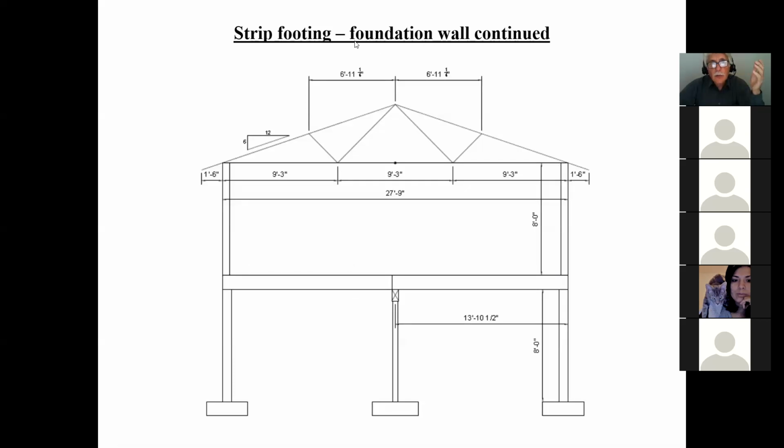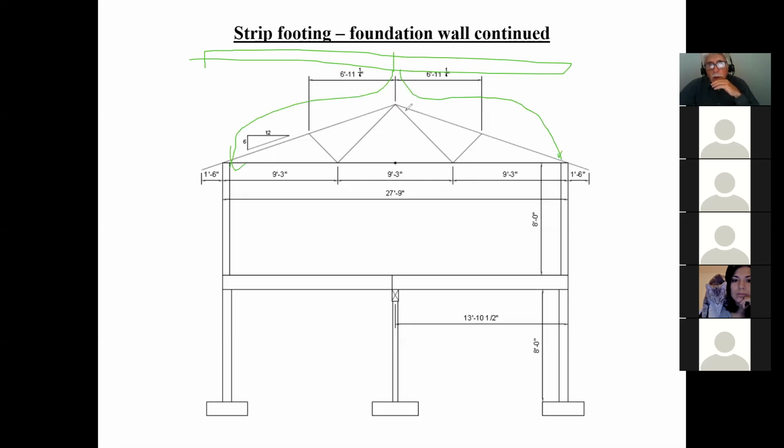So here is what you have to remember, okay? All the snow loads up here, I know that this is going to go here and this is going to go there. All the load of my roof structure here is going to go there, and all the load on this side is going to go there. So therefore, that's the load path of how the loads are going to go down. Then the loads here are going to go down the wall. All the loads on the floor here are going to go through here, and eventually, they have to be resisted by the soil here.